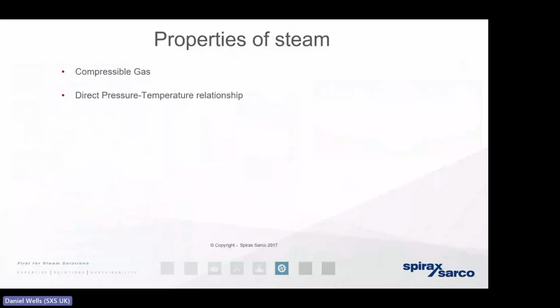So it tells us why those two-port self-acting pressure-reducing valves are very, very attractive to managing the energy relationship with steam. But it also tells us why those pressure gauges are also critically important.